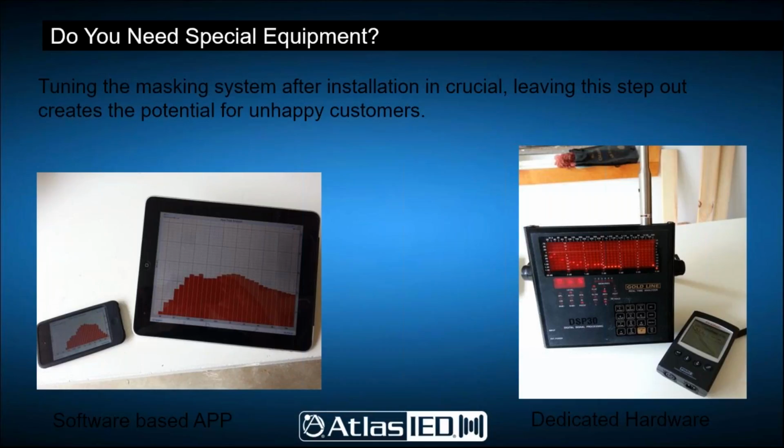Do you need special equipment? The answer is yes. Tuning the masking system after installation is by far the most crucial step for a masking system. Too many times we've had a lot of people just go into the system, plug it in, turn it on, walk out the door. It's not specifically tuned.